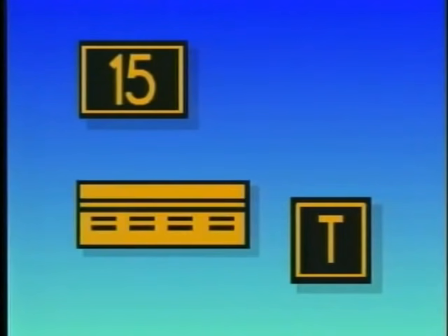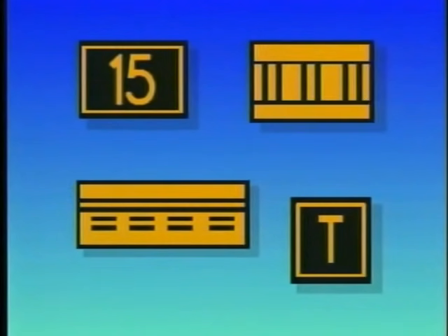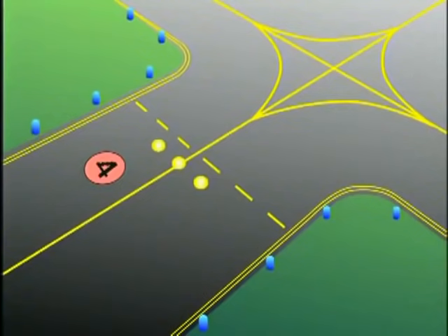There are three different types of location signs. The ones used to identify either a runway or taxiway have yellow lettering and a yellow border on a black background. Runway boundary and ILS critical area boundary signs have black markings on a yellow background. Geographic position markers are pink with black lettering and identify a specific location on a taxiway.